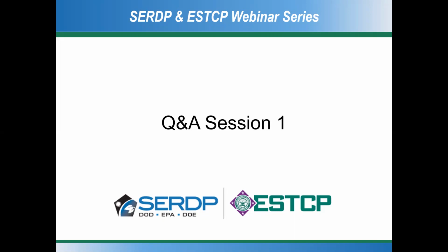Even though you have a long history of pumping data without a clear pumping test or a long period with steady pumping, you can use signal processing techniques to extract the transfer function or the unit response function from the historical measurements. One of the techniques we used for a Navy site is transfer function noise. So you can look at the dynamics and extract the unit response function from the historical measurements, even though the pumping has been cycling on and off irregularly over time.